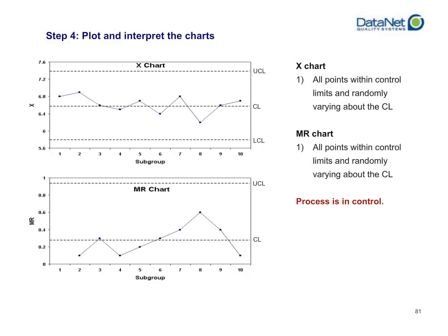and it came down naturally again. So this is an example of where you really want to exercise discipline in not tampering with your process and allowing for natural variation, not trying to control your process when it doesn't need to be, when there's no assignable cause in play. You would have made things worse likely if you had tried to adjust somewhere around subgroup number 8. You would probably have caused your values to actually fall below your lower control limit, and maybe even below your spec if you were not being careful.